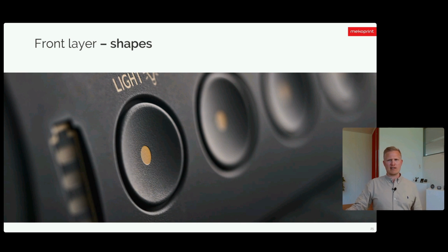Shapes and level design in your keypad is also a way to enhance areas of the keypad, especially in situations where the keypad is operated with gloves or without direct eye contact. This can be useful. That's where tactility through level design of the buttons can give a great UX. And that's where silicone rubber has its strength compared to other keypad materials. And here's a good example of concave keys, which makes it easier for the user to locate them if they cannot see them when pushing the buttons.